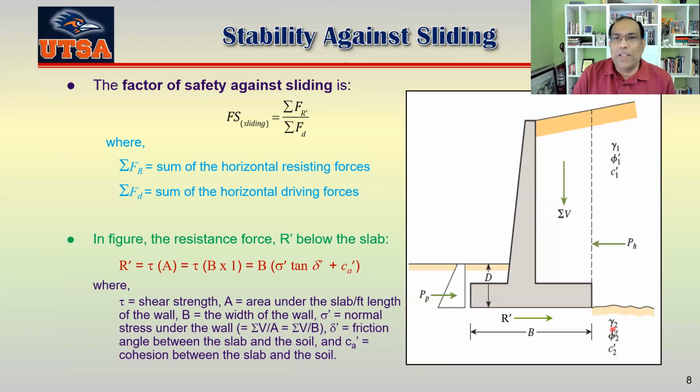After constructing that one, we refill that one, but this is basically the foundation. In your last exam, I saw that many of you actually confused this soil and this soil. Okay, this is the foundation soil. So you have to consider this foundation soil for sliding and bearing capacity. On the other hand, the soil here, the weight of this soil, is responsible for creating the active force along the line AB. Okay, so two different soils, refilled soil, and this is the foundation soil.